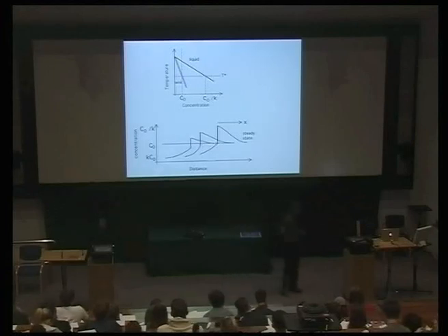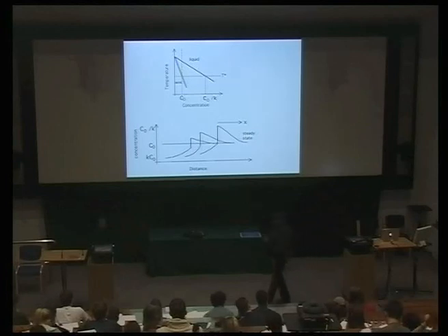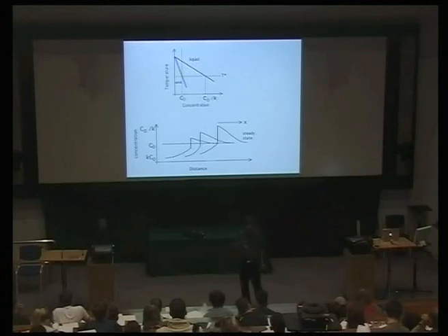And notice also that I'm dealing only with binary alloys. Yeah, so we have only one solute. A real material might contain a dozen solutes deliberately added to control the properties. So we have to think about multi-component diffusion and how one solute species keeps pace with another solute species, because there's only one interface moving. Okay?